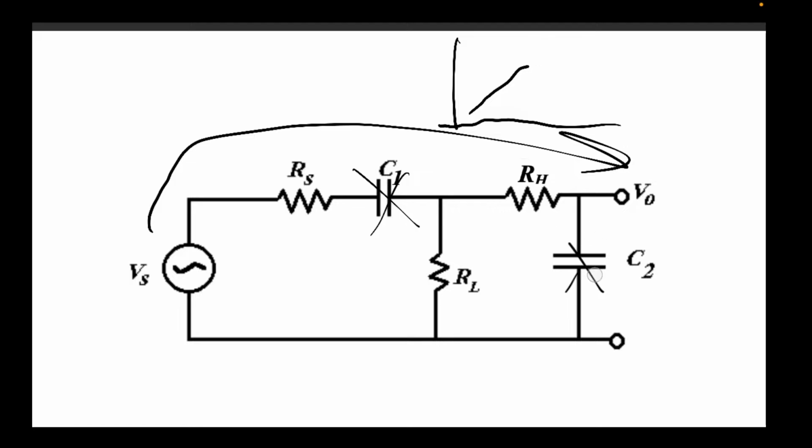Then, if I considered high frequencies, this would be shorted, and this would be shorted. Well, what is V out over a shorted capacitor? Would that also be 0, right? And so you've got this gray area in between where on one side they're both open and on the other side they're both shorted. In each case, what you see is that they are going to 0.